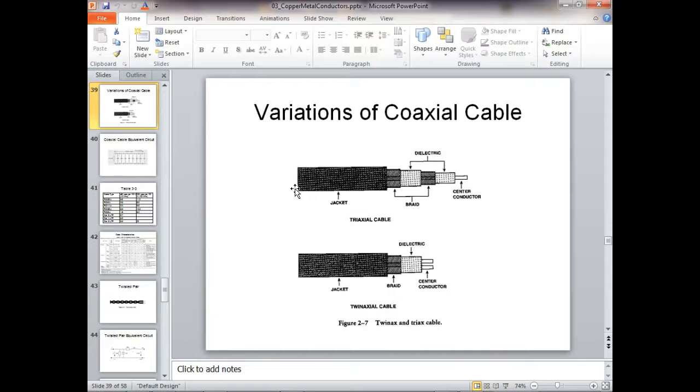And our ultimate goal in a communication system is to get what we call impedance matching. We looked at that, right? What happens if all the impedances match? So we went up there, we threw up all them different resistors. We had an internal signal source that had 100 ohm worth of resistance because it's easy to see resistance. And then we put about 4 or 5 different loads out there, 3 different loads, and we saw when we got the maximum transfer between our transmitter and our receiver.